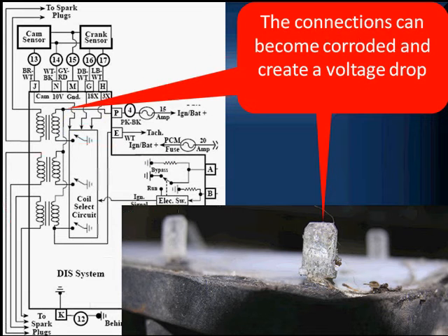Now, let's talk some more about this. All these connections we talk about, we've mentioned it for years and years. I don't know how many times we have solved problems by saying coil is low. Let's start off into the routine checks. Let's check so we got good contact. Look at this corrosion on this particular connector. This is just something we found one day on a car that could not be fixed because it had a misfire under load. I wonder why.